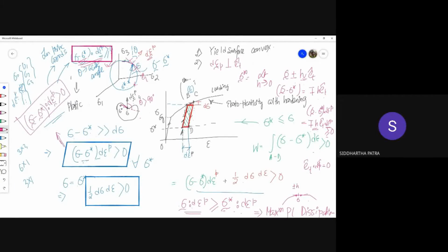Okay, this is just the reverse of this statement right here. Here we are talking about the plastic strain being normal to the yield surface, so we are characterizing the plastic strain, whereas here we are talking about the possible stresses. Of all the possible values, the stress assumes only that value that would, for a given plastic strain increment. Or here we are talking about a given stress. For a given stress, the plastic strain increment is normal to the yield surface.